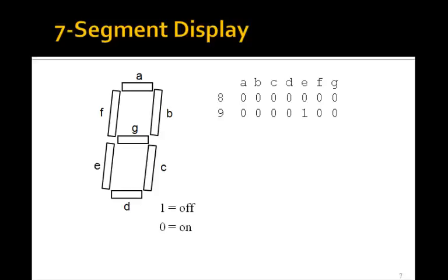A, we just turn off the D. So we turn off the D, we'll have an uppercase A. And what about B? We obviously can't make an uppercase B because that would look like an 8. So we make a lowercase b by turning off A and B, putting 1s on A and B. So that's a lowercase b.